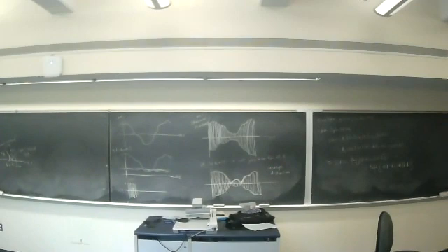So, let's say this is AM radio 1200 kilohertz. Okay. And so AM 1200 is transmitting using a carrier frequency of 1200 kilohertz, 1.2 megahertz. Okay. The next radio station, the next allowed radio station in the area would be at 1210, right?